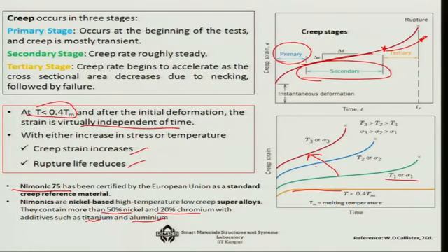And I will not go into the details at this moment, but there are various mechanical models that are used actually. A very common model is something like a spring, a material model, and a dashpot combination in series. Okay. So, and the load is coming here. Okay. So, this is a spring K and this is a dashpot. Okay. So, imagine that you are applying a load F and how this system will be behaving. Okay. So, that is something that approximately simulates the creep behavior of a system.